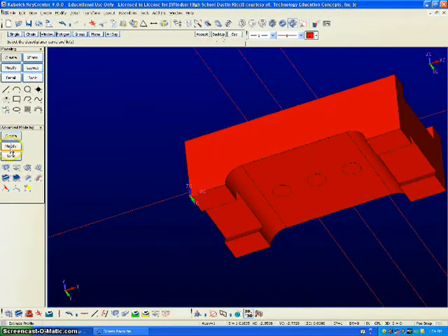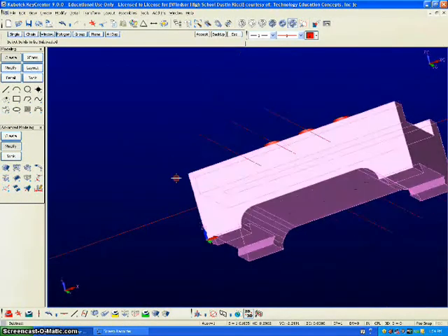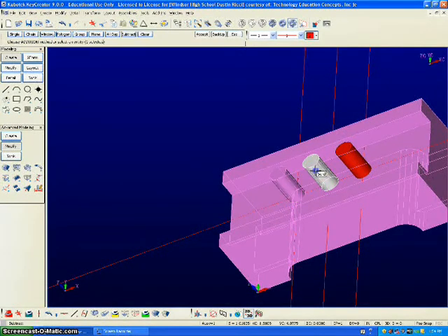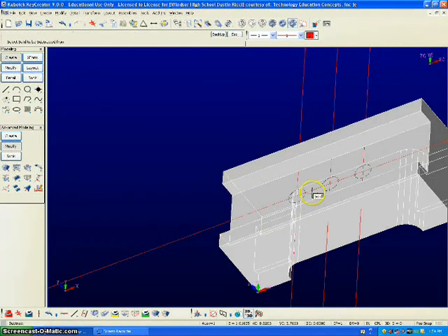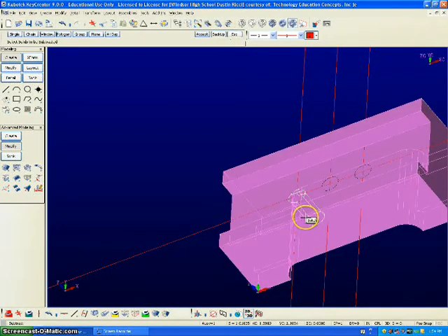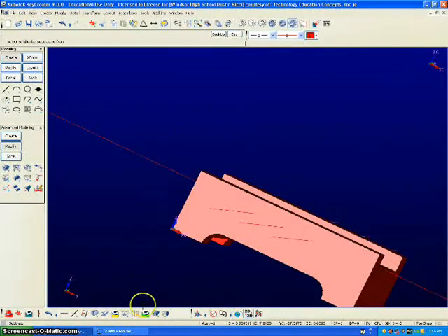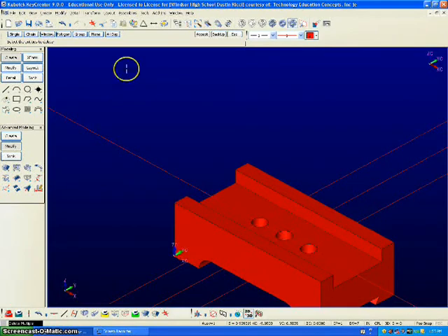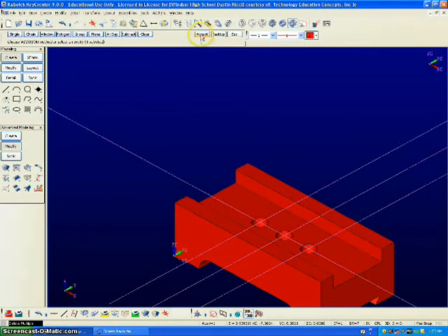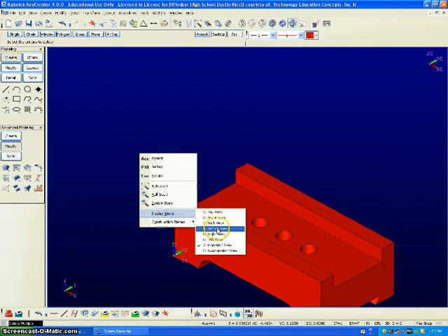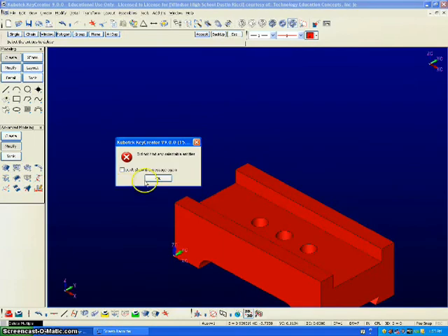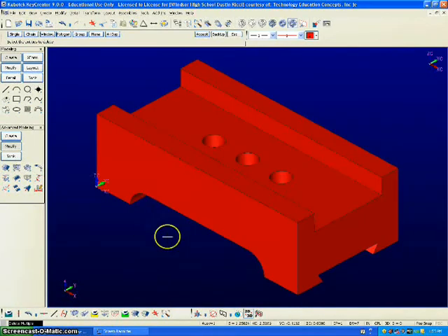Accept, and we're going to use the subtract tool, modify boolean, subtract, select the solid to be subtracted from, which is the main block, and then the 3 cylinders we just made, and then that deletes it so they're up to the block's face. So we're going to do that one more time. So we're going to select the main body, and then the 3 smaller cylinders, accept, and there you have it. That's all done. Now let's just clean it up a little bit. So delete multiple, and let's delete these lines we just created, accept, and Control A to center our block.